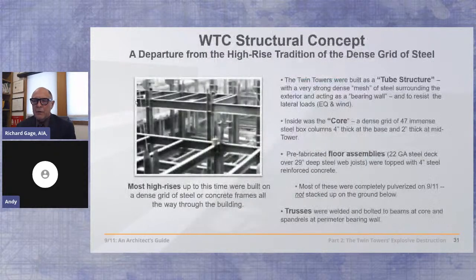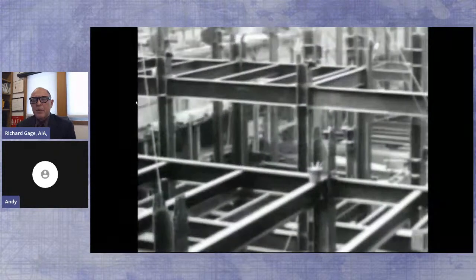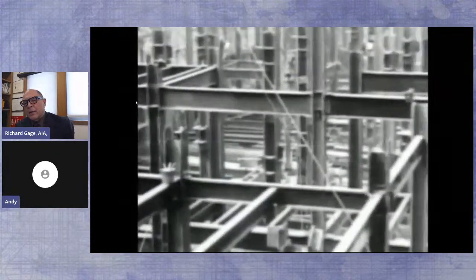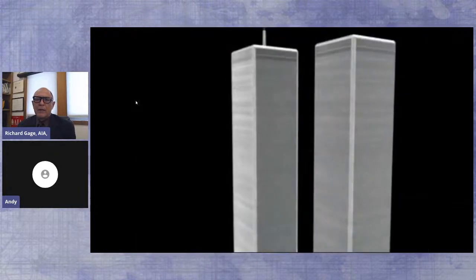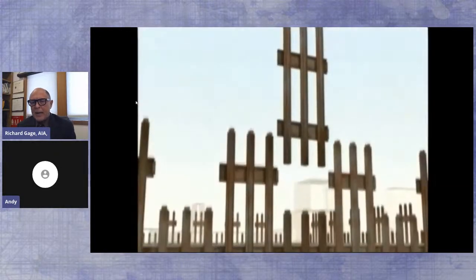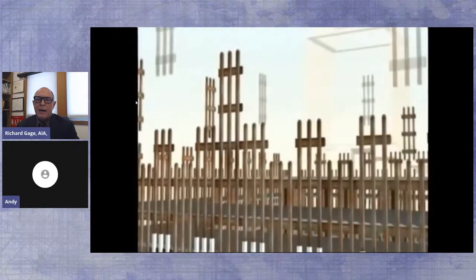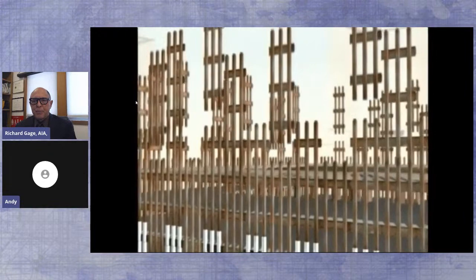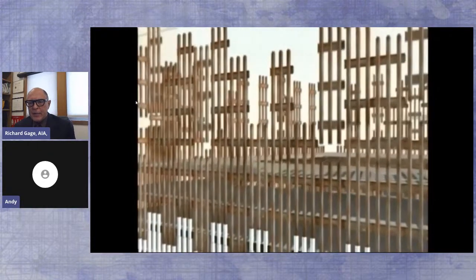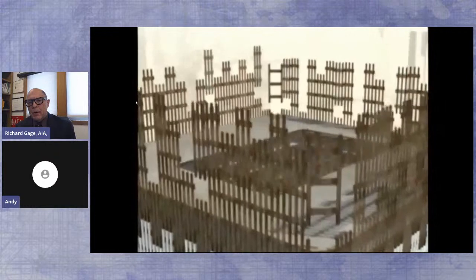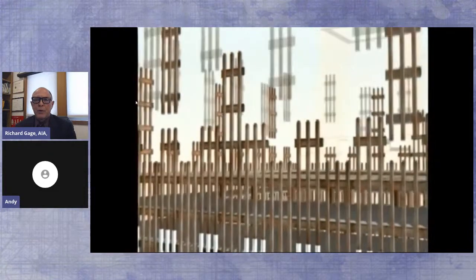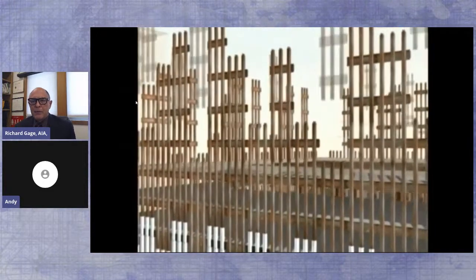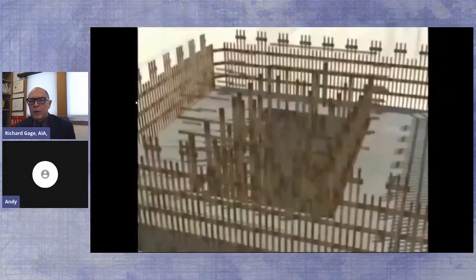That was a novel concept, as was the structural innovation here, because up till this time, the skyscrapers had a forest of columns, severely impacting the layout of the spaces, including the Empire State Building. What they did with the Twin Towers was push half the columns out to the outside and group the rest of them on the inside. So the outside is a perimeter structural steel system, some call an exoskeleton, with 3 horizontal spandrel panels welded in the factory to 3 vertical columns.